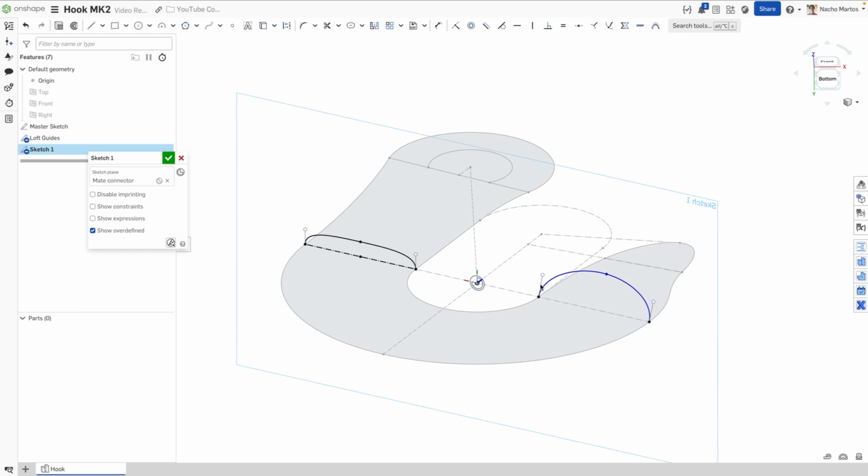We're going to select this spline line here, vertical, spline line here, vertical. We will then define a line and a construction piece of geometry that goes across. We will make a point. We can select point. We'll put that point at the midpoint of the line. We select both points. We make them vertical. We select these 2 points. We make them horizontal. We're just evening this geometry out.